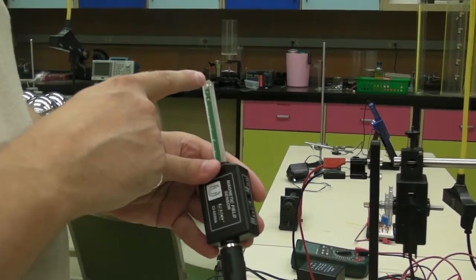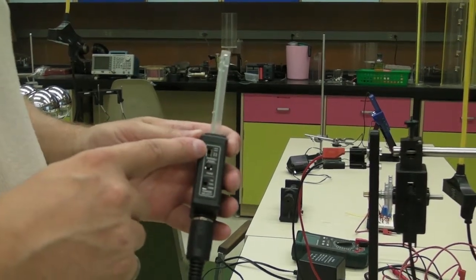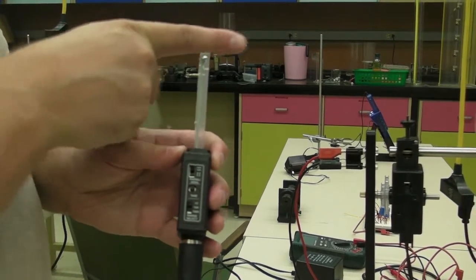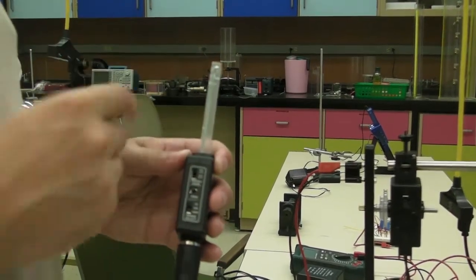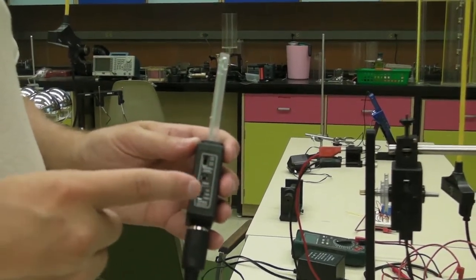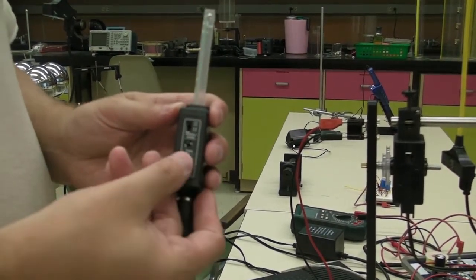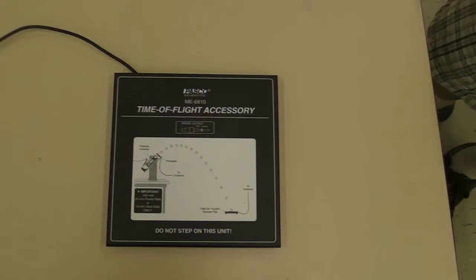This is a magnetic field sensor. It measures the strength of the magnetic field at the tip of its probe. There is a switch on it that controls whether it is measuring radially or axially, there's a tare button to zero it, and there's a sensitivity switch that controls whether it is operating at 1 times, 10 times, or 100 times.